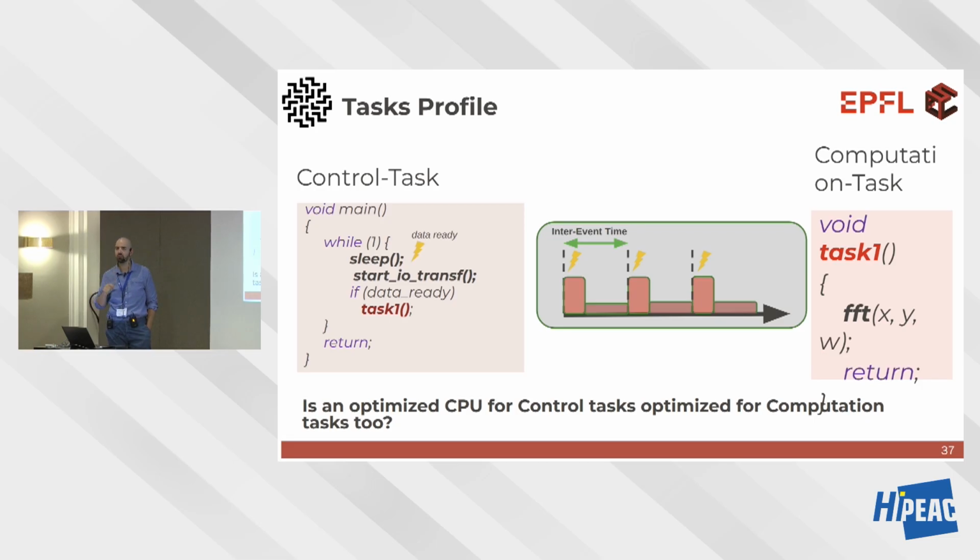Okay, more leakage power. If it's out of order and you get extra performance from that, that doesn't matter much if you're spending most of the time sleeping anyway. Similar to your colleague's explanation, you're wasting leakage power. Although in sleep mode, theoretically, you can also power gate, right? So in that case, you won't consume any leakage power, but you consume area. So your chip is more expensive, but you don't really need to make it that big. But those are pretty much the reasons.